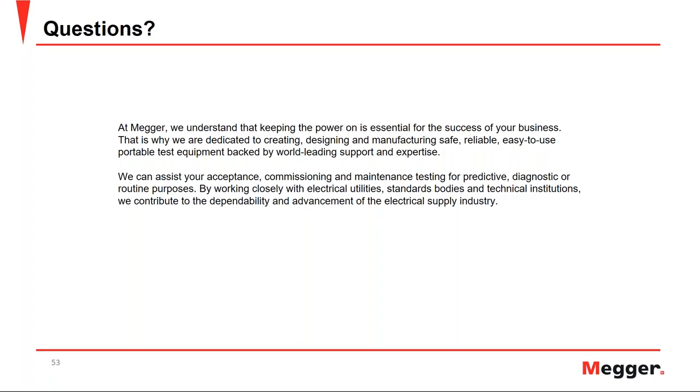Without moving into other testing, you have a way to investigate the insulation right there on the spot while you are testing, without waiting a couple of days for oil results. You can get more information from the transformer with the same test instrument. That's what narrowband DFR gives you: the ability to see a wider spectrum of the condition of the insulation with one simple test that takes a very short time to perform.